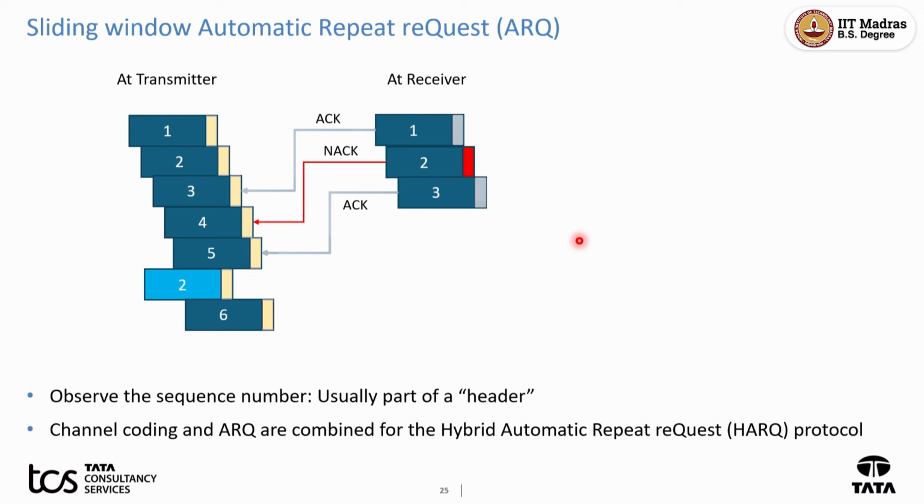This sequence number, that 0, yes sir. It adds it to the bits. Earlier he asked the question about if I want to send 00, 01, 11, 1011, the transmitter puts a 00. After that 0, 0, that is for the signal. For the bits, it will put a sequence number in front. Transmitter will put the sequence number without telling you. Receiver will use that sequence number. It won't pass that signal which is helping you to get the start of the transmission, nor will it pass the sequence number which it has got there.